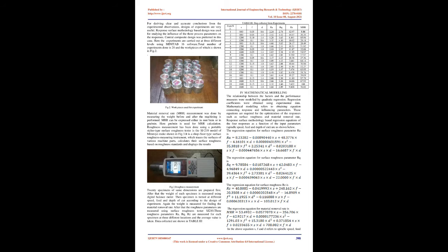Feed rate is the dominant factor affecting surface roughness, which is minimized when the feed rate and depth of cut are set to the lowest level, while the cutting speed is set to the highest level. D. Philip Selvaraj et al.